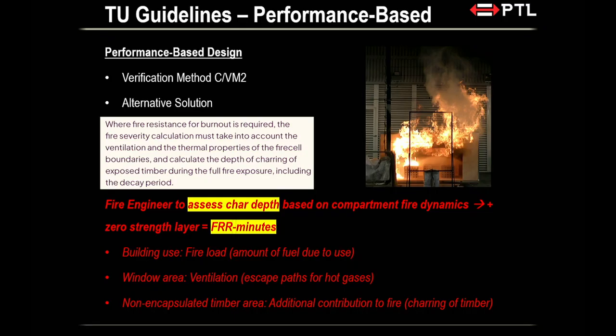So when we do performance-based design, the fire that we're talking about is a burnout fire. What is a burnout fire? A burnout fire means that fire ignites, grows, gets to peak, has to decay, timber has to stop charring. That's it. You have to design for the full spectrum. Okay? It's not like, okay, I have sprinklers, so my fire will never proceed beyond that. Or at the end of fully developed, I have firefighters coming in, putting water on the fire, so I don't have to design. There's no latitude for that. You have to design for the full spectrum.